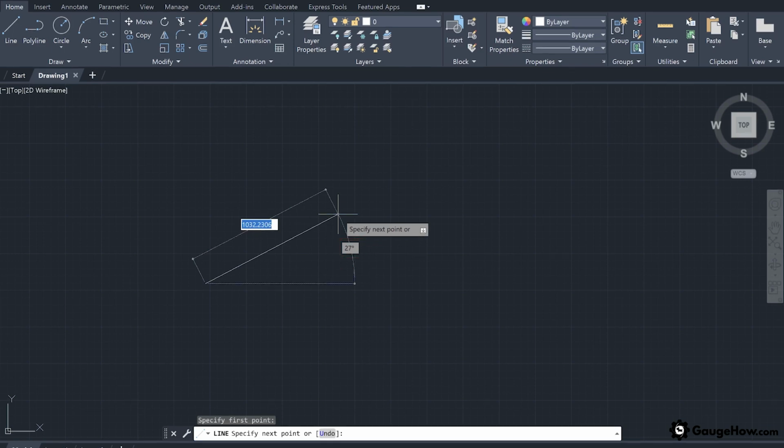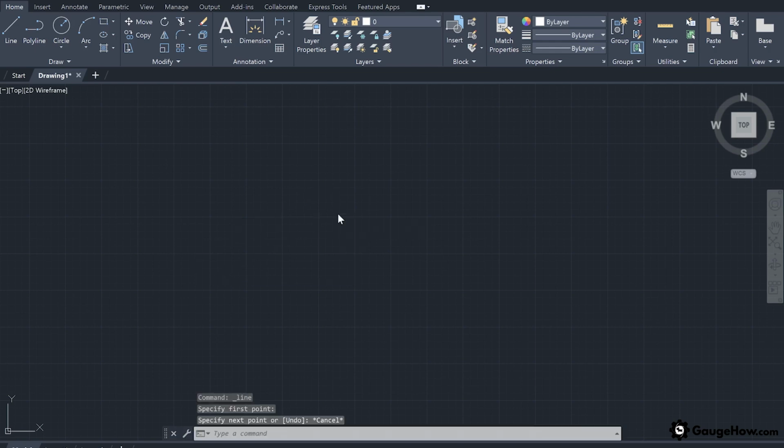Now you can see that two options are available, but what if you are not familiar with the dimensions? So again, hit the escape key, and as we have already discussed how to set the units, from there you can check the units available for your drawing. Here we have selected the acadiso file so that we can draw our design in metric units.